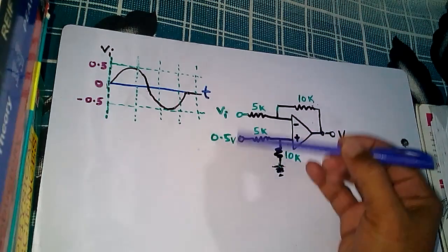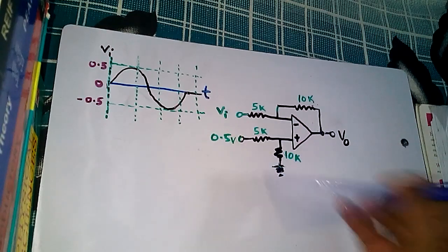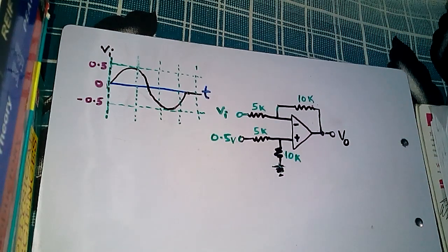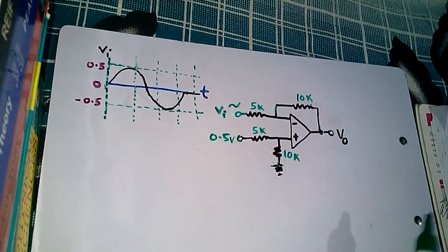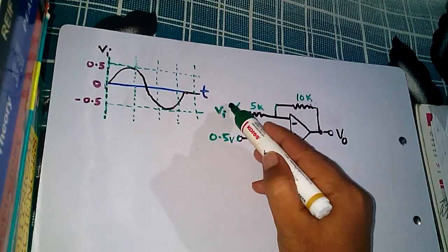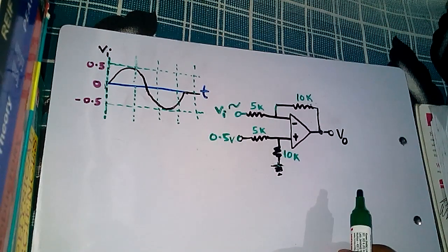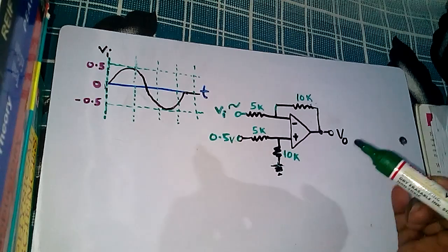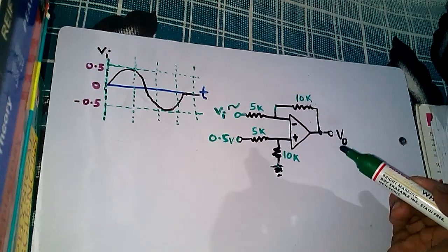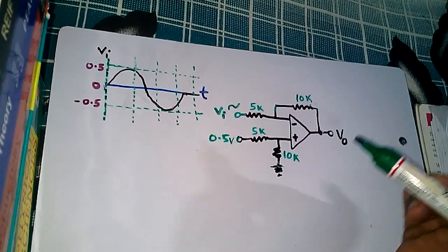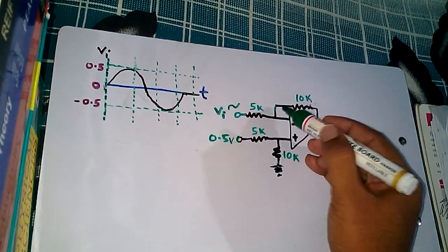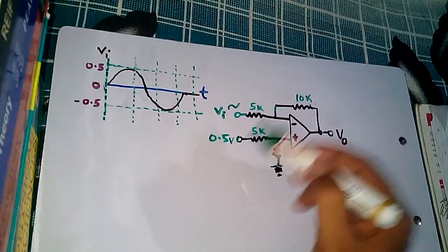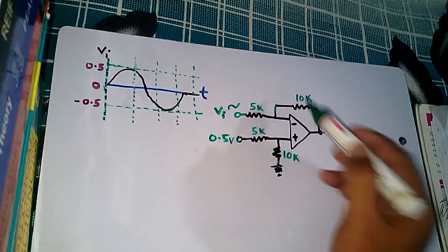because we can see two input voltages. Two input voltages are possible only for a differential amplifier circuit. We know this. So this is the differential amplifier circuit. What configuration? With open loop or with feedback? This is the differential amplifier circuit with feedback. Clearly we can see here is a feedback circuit. So two input voltages, four resistors and feedback.